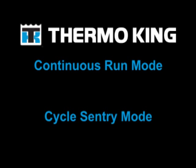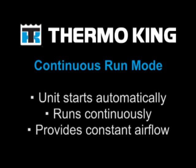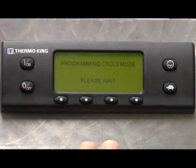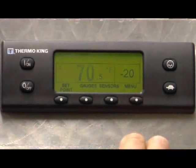SR2 units can be operated in continuous run or cycle sentry start-stop modes. When continuous run is selected, the unit starts automatically and runs continuously to maintain set point and provide constant airflow. When cycle sentry is selected, the unit will start and stop automatically to maintain set point, keep the engine warm, and the battery charged. Not all temperature-controlled products can be properly transported using cycle sentry operation. Before selecting cycle sentry operation, be sure the cargo is approved for cycle sentry operation. When in doubt, use continuous run.